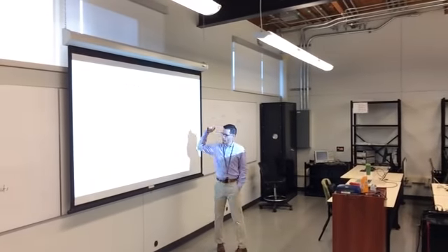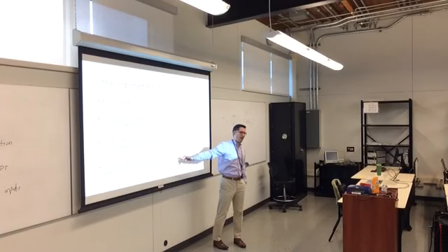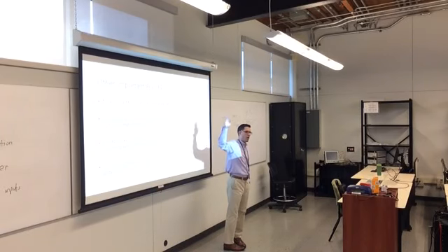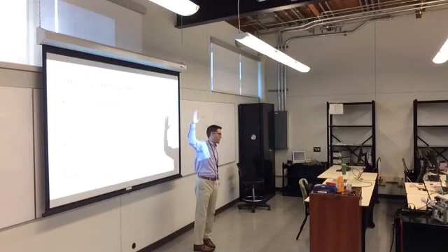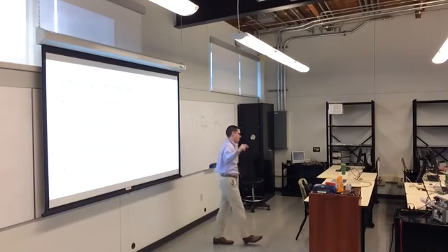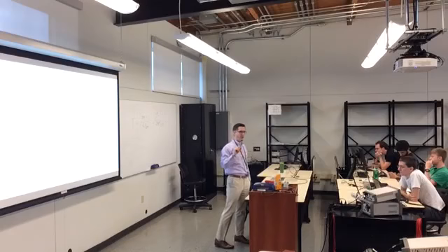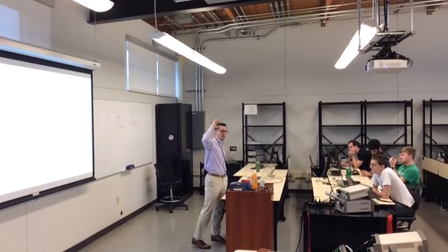When a flag goes high, you're going to need to clear the flag. Otherwise, your processor is going to sit there and go, oh crap, it's overflow, oh crap, it's overflow, forever. That is a common mistake. I can guarantee when you start to do work on timers, you're going to forget to clear the flags, and you're going to sit in your interrupt handler forever. If an interrupt occurs, your processor is not running its main program. Interrupts occur in sort of a privileged space.